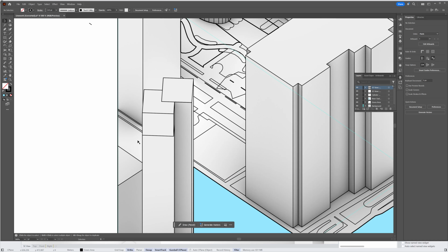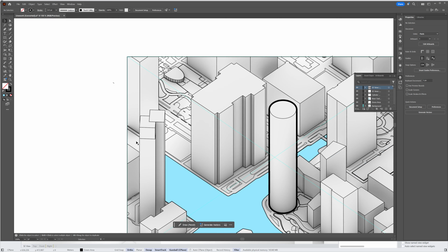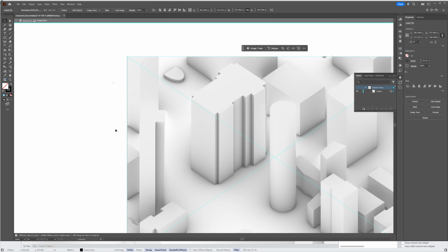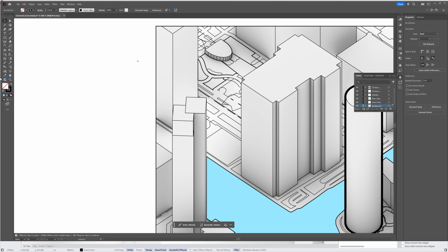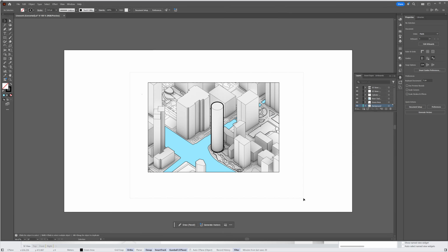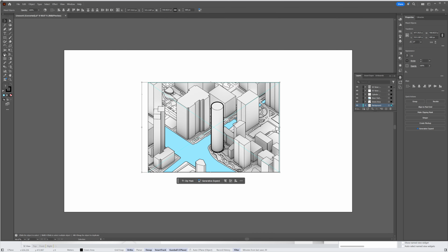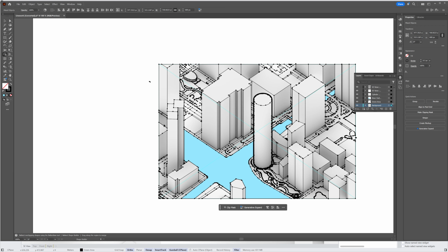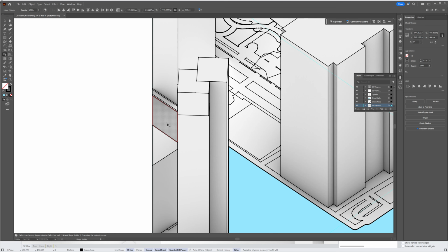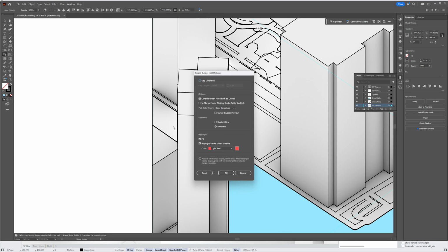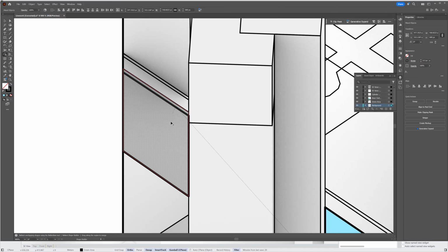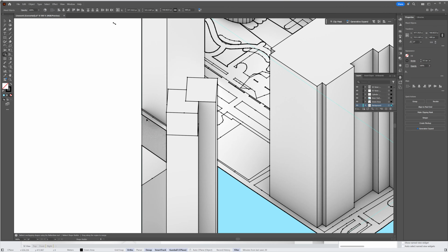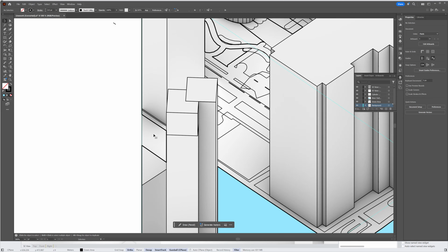If I missed some as well, which I think I missed this area here, I can also begin to create a shape there. And the way I can do that is by selecting all of my lines and going to shape builder here. This is similar to the curve Boolean tool, where I can just select inside there, hit enter, and click OK. I'm just going to go shape, and that should now create an outline there.